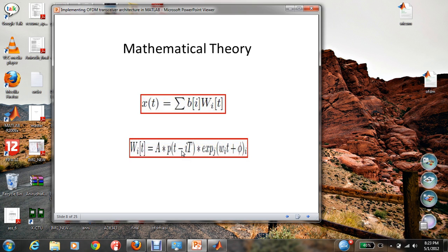That is the frequency, that is the bandwidth should be such that the channel should receive a band limited signal, and it should also follow the Nyquist criteria, in order to avoid intersymbol interference. So for that reason, the transmitted signal should be pulse shaped. And this is the exponential part, which shows a carrier.